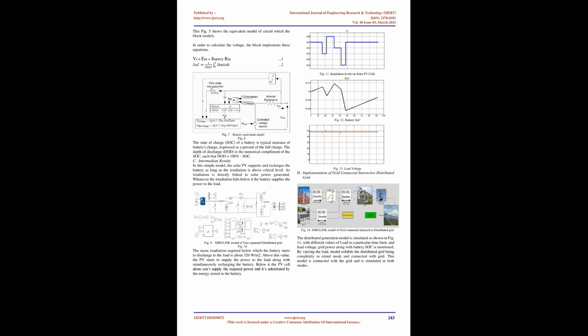In this method, a small disturbance is made to cause power variation in the photovoltaic module. The photovoltaic output is regularly taken and compared with the previous output value. If output solar power rises, then the process is resumed, else the perturbation is reversed. The solar module voltage is changed as increase/decrease to see whether the output power is increasing or decreasing. If a rise in voltage points to a rise in power, this shows that the operating point of the photovoltaic is left of the maximum power point. So, more perturbation is needed toward the right to attain the maximum power point.